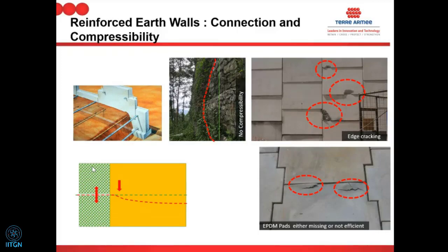And it is applicable for all kinds of facing. It's not just concrete. Even for our weld mesh or gabion, whatever we do, this compressibility has to be taken care of. Otherwise, the stresses at the connection point will be very high, and that can lead to serious problems. And that's why